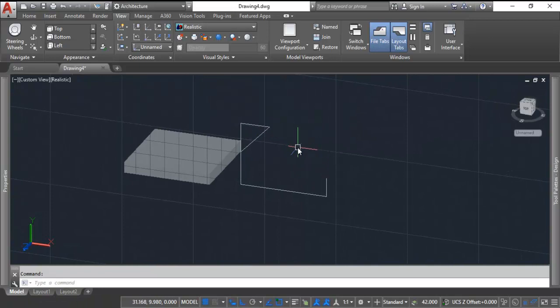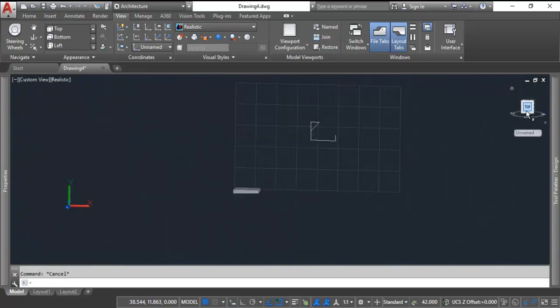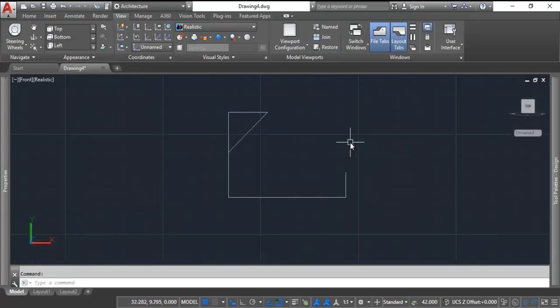So to finish this out, they don't tell us how wide the top flat is, so we have to draw another line from here. And I'm going to do a top view, so I'm totally flat when I draw this. So I went back into 2D. And I'm going to go shift at, I'm just going to pick a length of like 6 inches at an angle of, that would be 135.